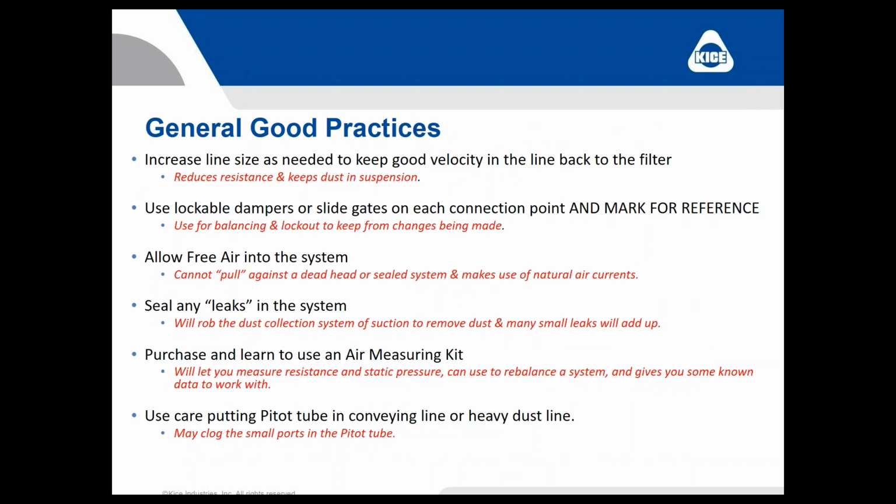General good practices: increase the line size as needed to keep good velocity in the line back to the filter. And we'll show this in just another slide right quick. But it reduces resistance and it keeps the dust in suspension. Use lockable dampers or slide gates. Mark them, even if it's just a Sharpie mark. At least you can say, this is what it was doing when it was working.